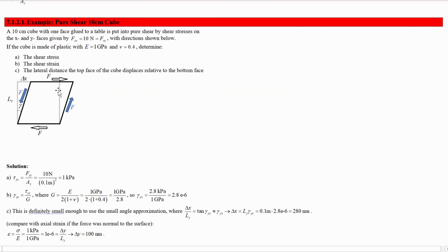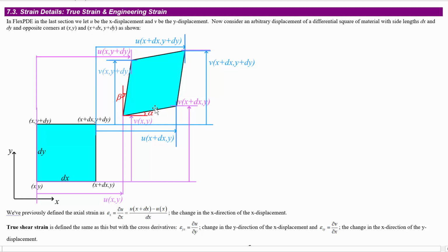But that seems a little bit strange, because what if you just take this thing and you rotate it up a bit, and you've got all the displacement down here as this angle, like it was this side that's fixed instead, right? So this is a way to account for that and deal with the difference. We're really looking at the change in this angle versus this angle, yeah? Now, if the thing just rotates, we can be deceived because we'll have a large beta angle, which is showing up from the thing rotating around, even though alpha is negative. There isn't actually any strain in that, right?